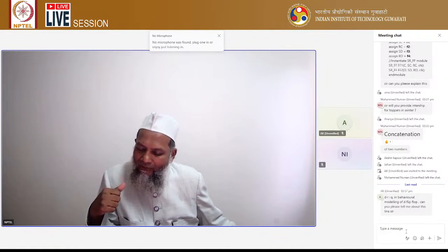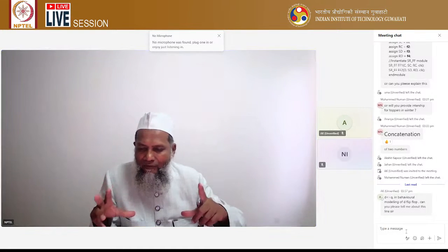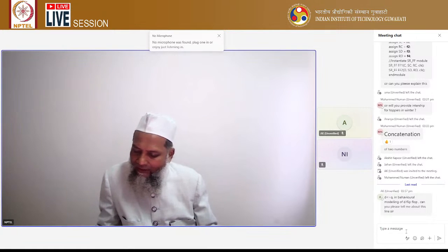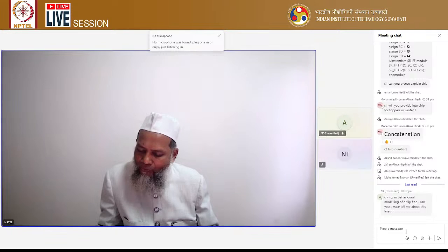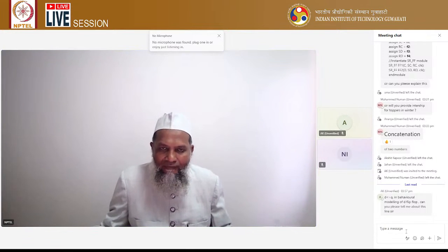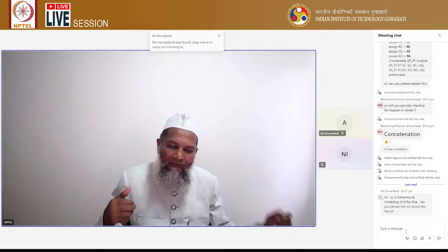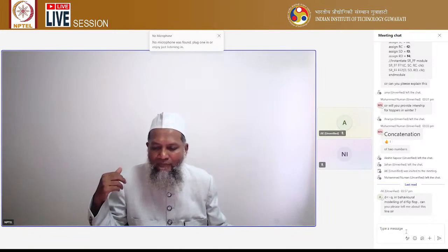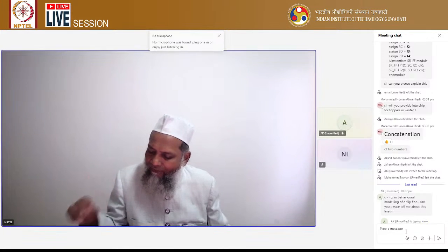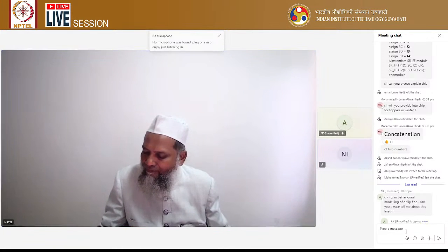Whereas in non-blocking, we can execute more than one statement in parallel. So the less than or equal to symbol is like this, and D we are assigning to Q. Because in a D flip-flop, basically output is equal to input. Suppose I apply the clock signal, whatever the input is will be transferred to the output. So Q is the output and D is the input. So for a D flip-flop, output is equal to input.